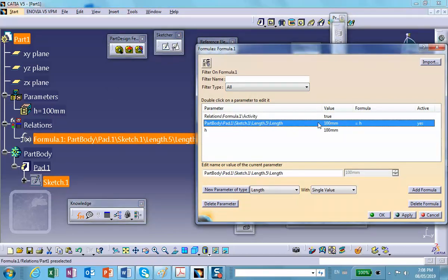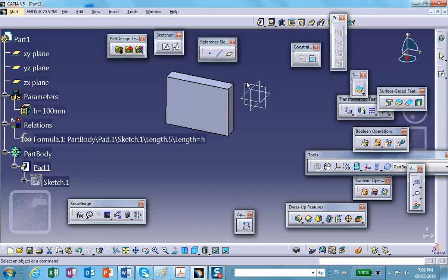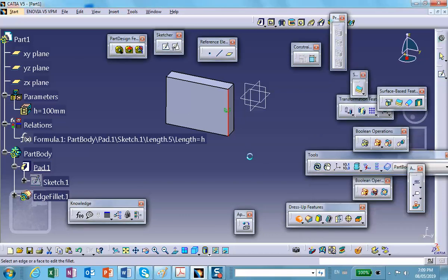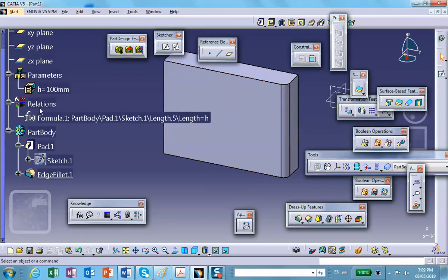One other thing, sometimes you see your true or false for something. For example, let me show you one. Let's say that we go and make a fillet, a surface fillet on that edge. So for the fillets, right here, on the dress up feature. So let's say we make a fillet here. You can see that, right? Okay, good.